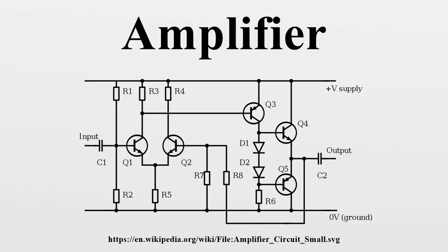An amplifier that is said to have a gain of 20 decibels might have a voltage gain of 10 times and an available power gain of much more than 20 decibels, yet actually deliver a much lower power gain if, for example, the input is from a 600 ohm microphone and the output connects to a 47 kilo-ohm input socket for a power amplifier.